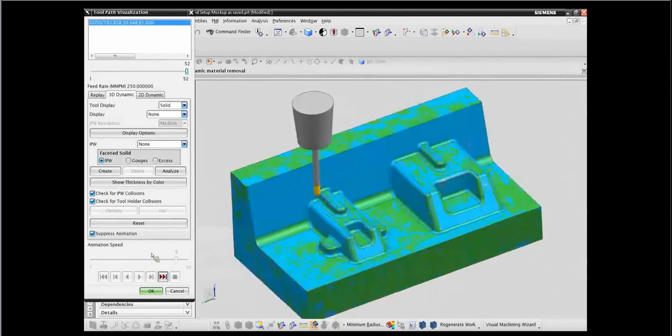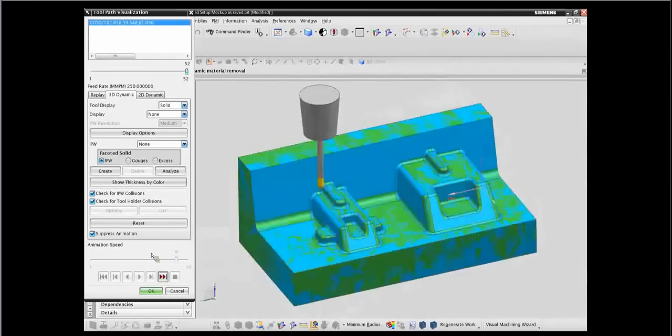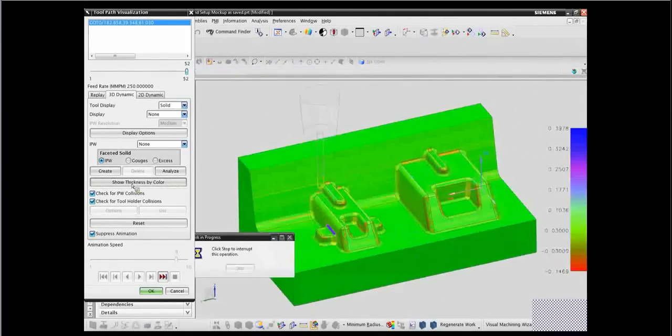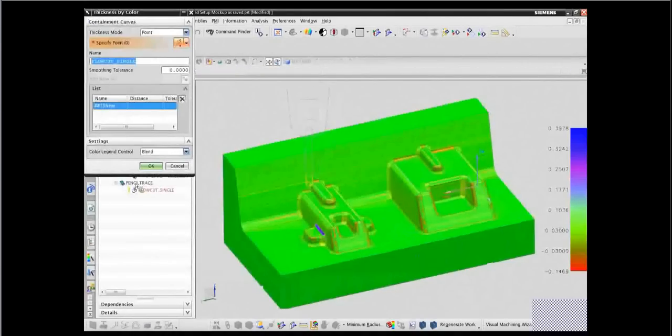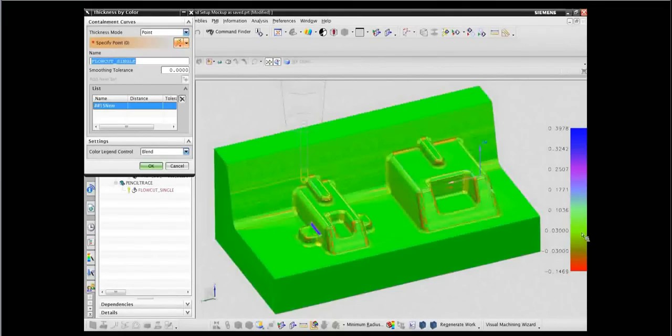Okay, so there is my in-process workpiece in its state as the machining is completed. And to the naked eye, it looks great. But there's actually a tool within NXCam to analyze the results of the machining compared to the design model. And what it does is it presents me with a view of colors, a hierarchy of colors here that gives me an indication of material thickness left on the part based on the darker shade of color. And if it's red, it means it's been over machined.